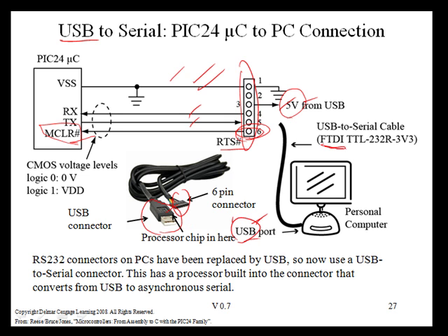I want to point out that with this particular cable, the voltage levels on these pins are 3.3 volts, so they're directly compatible with the VDD that we use for our PIC24 microcontroller. So we need no special chip to convert the voltages from this to this. They're compatible.